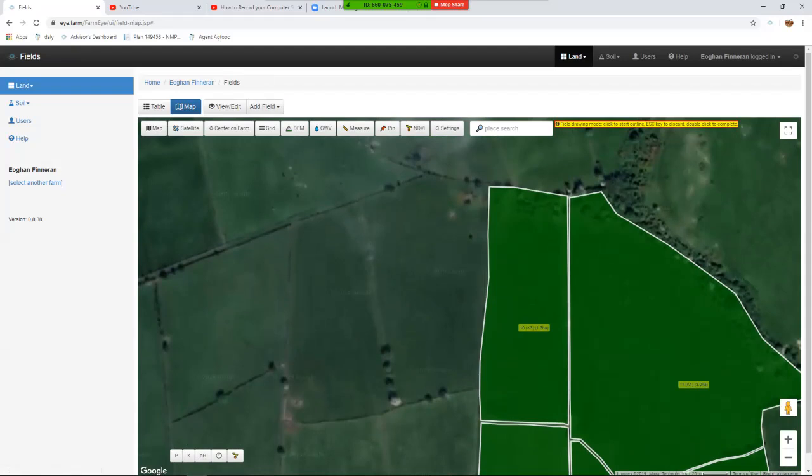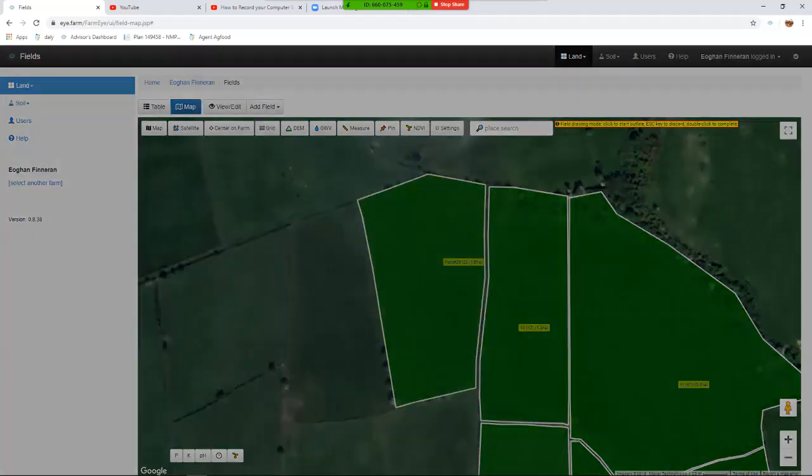So if you click on the corners of the field, when you come to an adjoining field, you don't have to be careful about drawing a line separate from the boundary of the existing field. You can actually click internally into the adjoining field and then come back out down here along the boundary of the field you're drawing, and then you double click to finish the field.